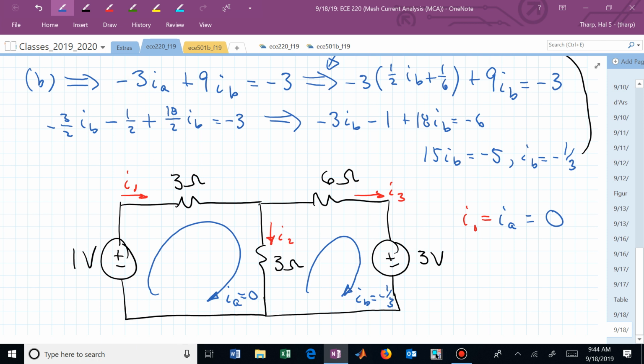So the top of that vertical 3 ohm better be the same as what's on the left of that horizontal 3 ohm, 1 volt. We'll see if we can check that. But there should be that same 1 volt source across that vertical 3 ohm resistor. Let's wait. Be patient. Let's see. What's I sub 2?